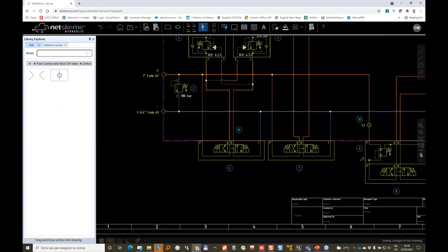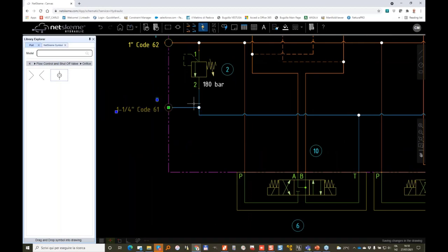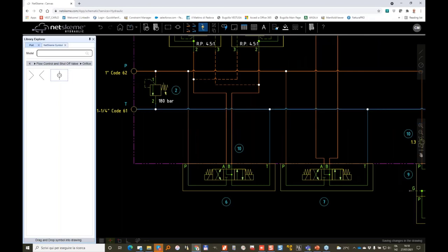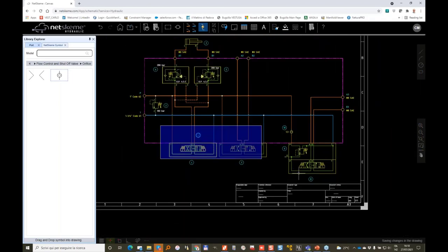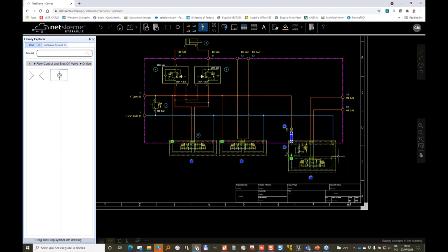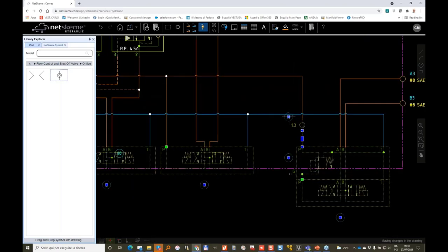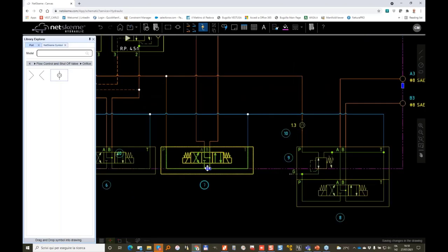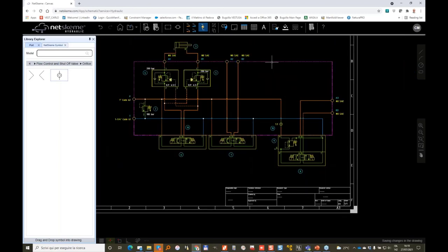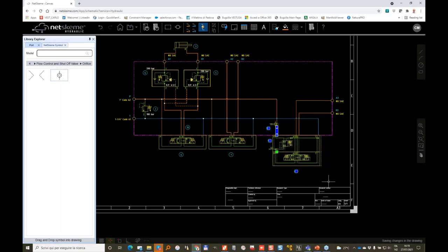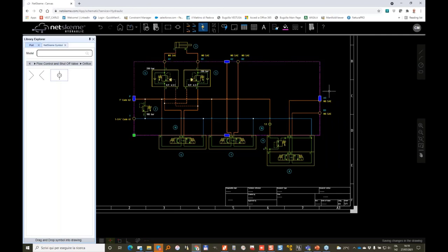And if we want to simplify our connection a bit, we can select an entity and this will change the position. We can stretch a line. And we can select several symbols. In this case, if we move the symbols up, the envelope line will not follow, but you can just stretch it after. And the same happens when we want to move the symbols to the left. The symbols will follow, and then we can stretch the envelope, and the ports will follow.